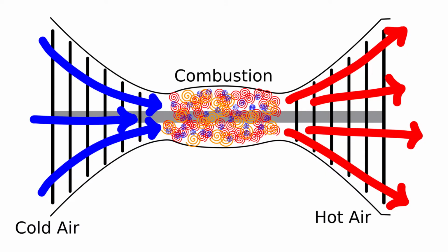Now my jet engine, like most jet engines, is going to run on the Brayton cycle. Technically an engine that uses the Brayton cycle is an open system. Mass goes in, mass goes out. Now that's hard to analyze. Fortunately, we can just treat the Brayton cycle like it is a closed system, and we just assume that the atmosphere is part of our system. Today we're going to be using that to look at some of the power output that our engine might have